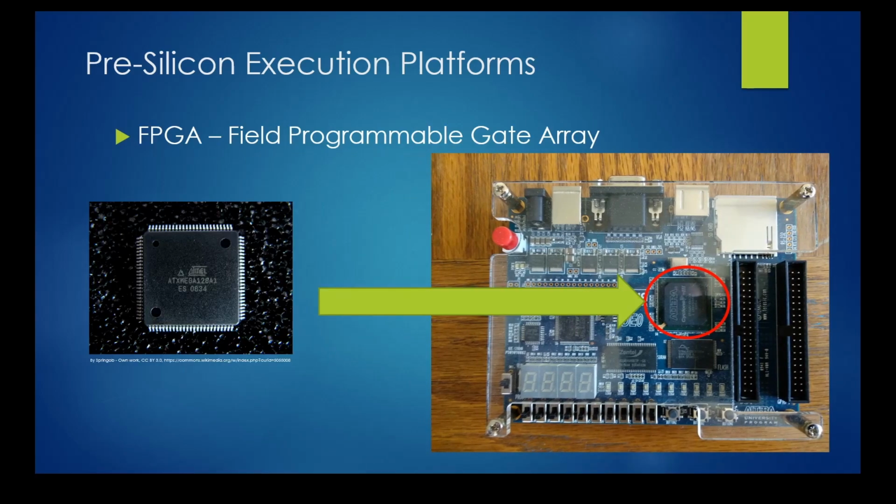For example, on the left, we have an Atmel ASIC with fixed logic, the AVR microcontroller. If we have the details of that logic, we can make the FPGA become an AVR microcontroller. For that reason, FPGAs can be used for pre-silicon development. While the hardware is still being developed, developers can take hardware logic that is not yet fully baked, put it on the FPGA, and create an execution environment that has a strong relation to the final hardware product.